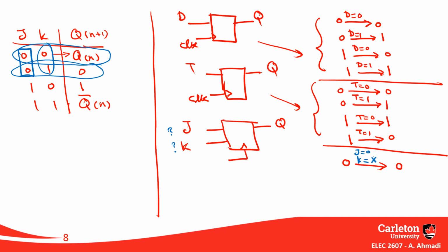Let's say in my example, I'm in state 0, S0. I want to stay at state S0 if input is 0. You remember that in the table? Now, to answer that, I have to think what keeps value 0 of my JK flip-flop as 0, and doesn't change that to anything else.